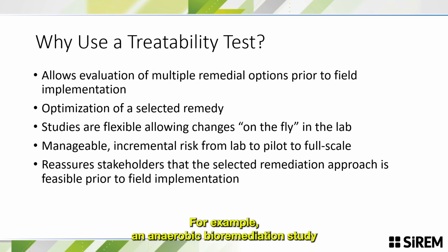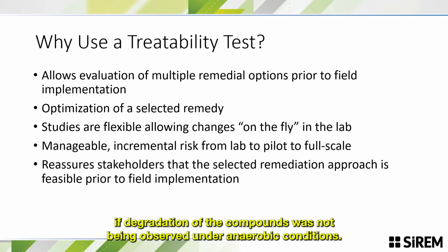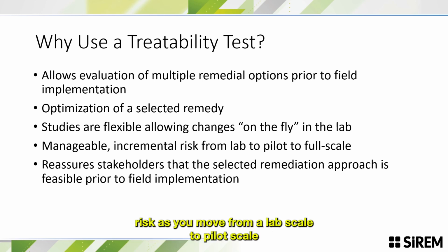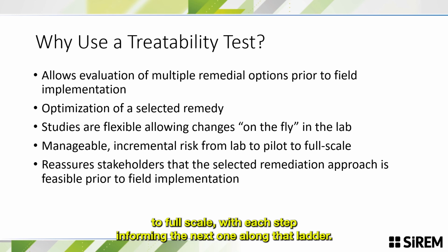For example, an anaerobic bioremediation study could be changed to an aerobic bioremediation study if degradation of the compounds was not being observed under anaerobic conditions. Treatability studies also allow for manageable incremental risk as you move from a lab scale to pilot scale to full scale, with each step informing the next one along that ladder.